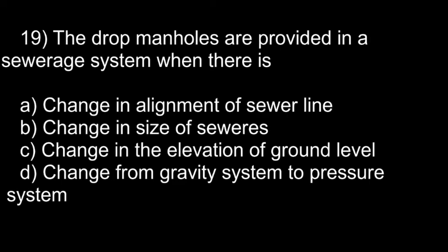Now let us discuss the manhole. A manhole is an opening in a sewer line to provide access for a man for the purpose of inspection and cleaning of sewer. The manholes are generally located at all changes of direction, at all changes of gradients, and at all junctions of main and branch sewers. The maximum distance between manholes for large sewers should be 300 meters. The essential parts of a manhole are a working chamber, an access shaft, cover and steps of iron.